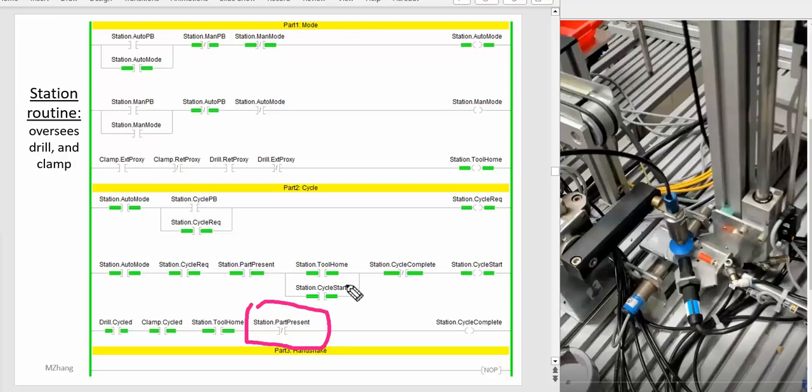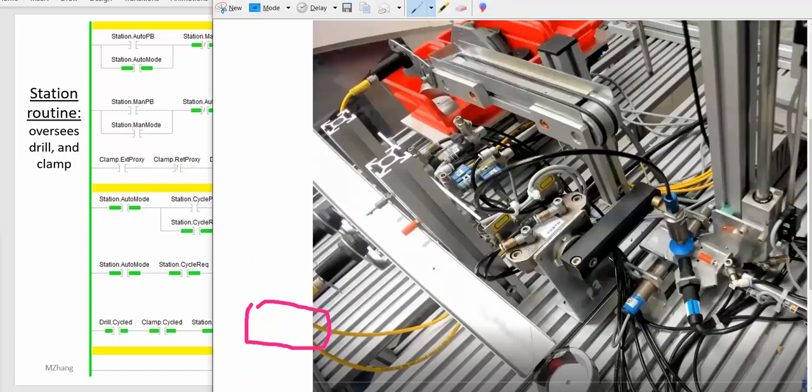So for example, let's look at the picture on here. So if you look at the sorting station pictures on here, what I mean, the problem is that if you have lots of parts, more than one part loaded on here, right? So when the part feeds one by one through station 1, your PartPresent is detected by these 2 sensors. If you have more than one part, then they are always on, right?